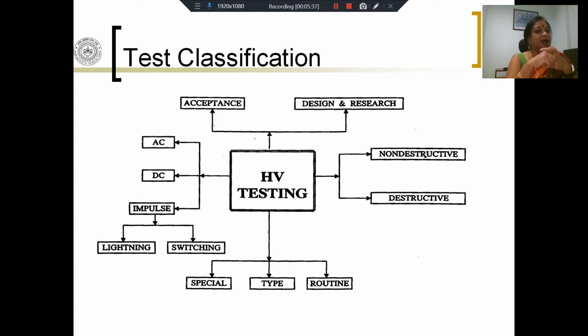But for any other kind of material, the insulation is not going to be self-restoring. So this is a destructive test, and this destructive test is necessary. But you may also understand that destructive tests cannot be done all the time and to a very large extent. For example, every equipment which is to be commissioned cannot be made to go through a destructive test because it